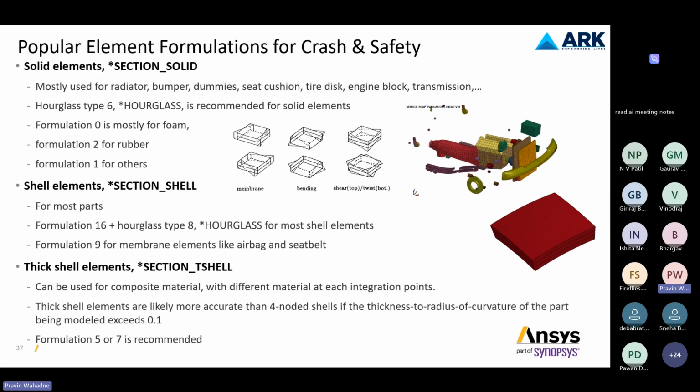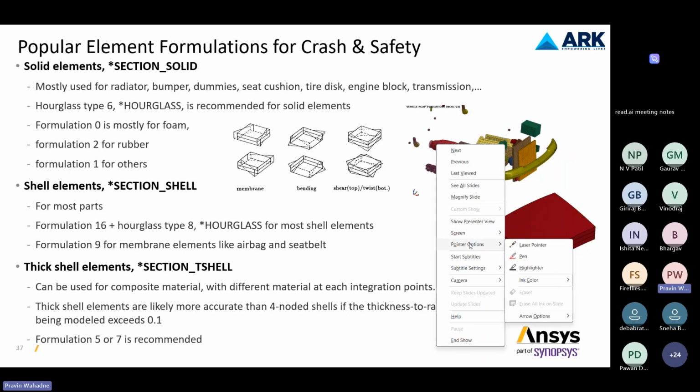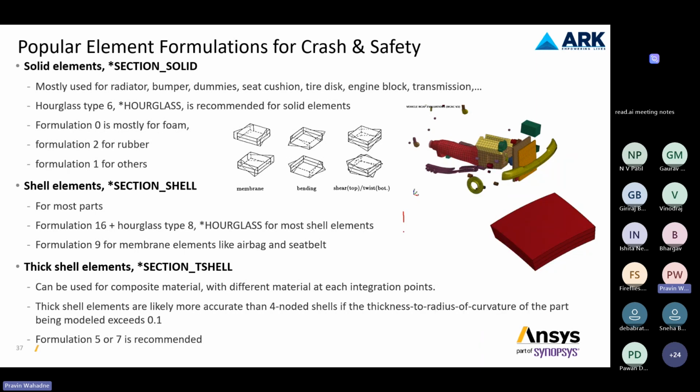Before creating any part in LS-DYNA, generally we need a part. That is *PART. Any part will have its part ID, then it will have the section ID, SID, that is the section which we are going to define, and the material ID.